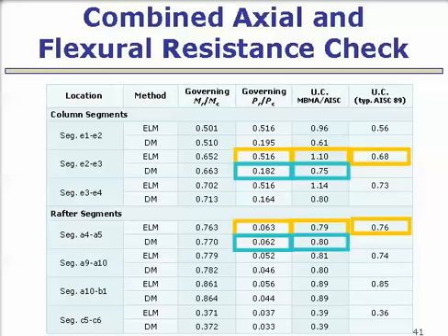And you've got to knock down your P sub C to deal with that leaning column effect because you're not dealing with it on the moment side. In the direct analysis method, you're getting amplified moments that handle that part of the design. So you design with P sub C based on K equals 1 or K equals 0. I showed you an example here.